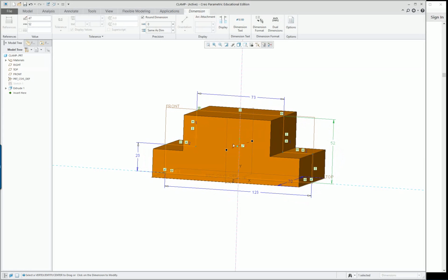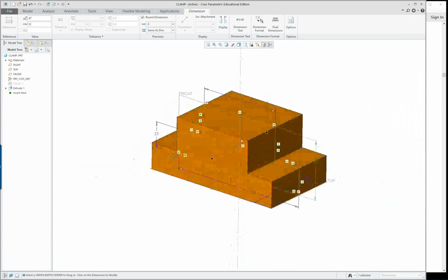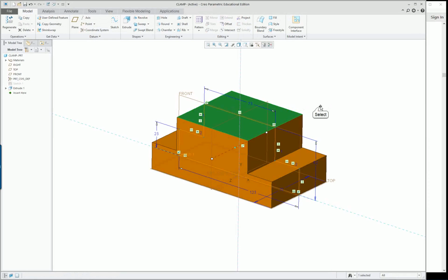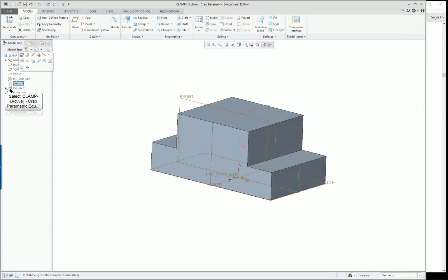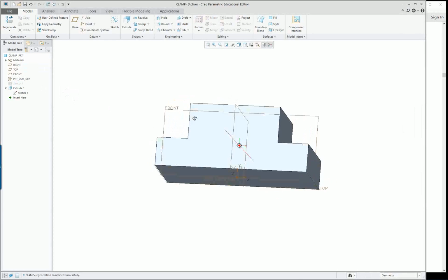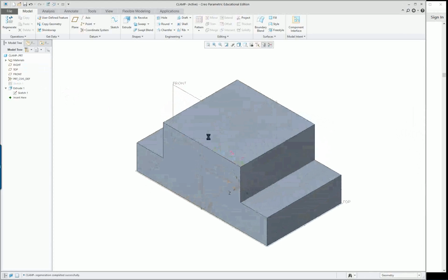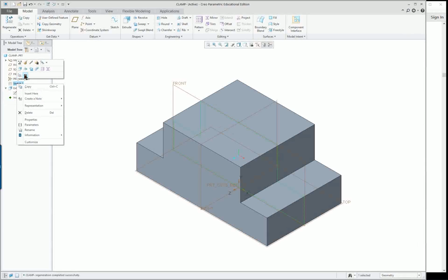So the editing here can be done once you're done with the first feature or when inside the actual sketch. In this case, here's the sketch. And you can notice I have the sketch here and I have the external sketch up here. So Control D, there's my model. My first feature is completed. Now, what I want to do here is I want to unhide this. So I click on it, right mouse button, and unhide my sketch.